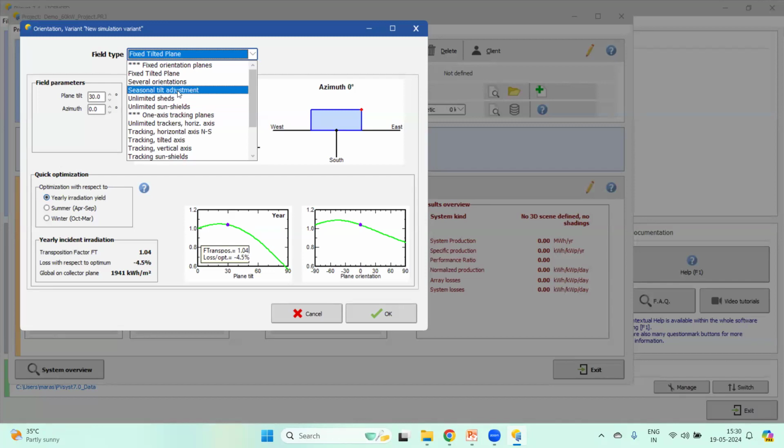In solar, during summers, because the sun is directly overhead, you don't have to tilt the module much. From latitude minus 10 degrees, a 10 to 15 degree tilt will be okay. During winters, because the sun is very low in the sky, you have to tilt more to receive more radiation.